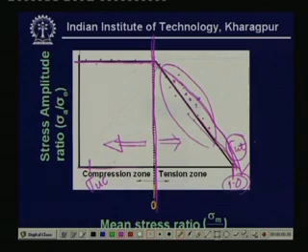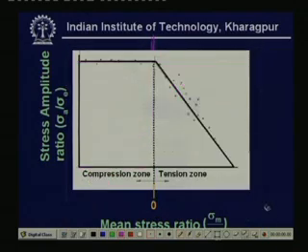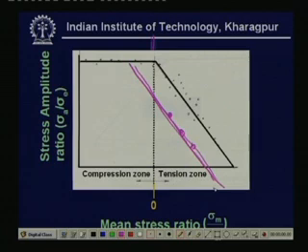And if one can model it so that you keep your stress always below such a line, then if your points lie over here away from this line and you model a safe line like this, your design will always be guarded against fatigue loading.